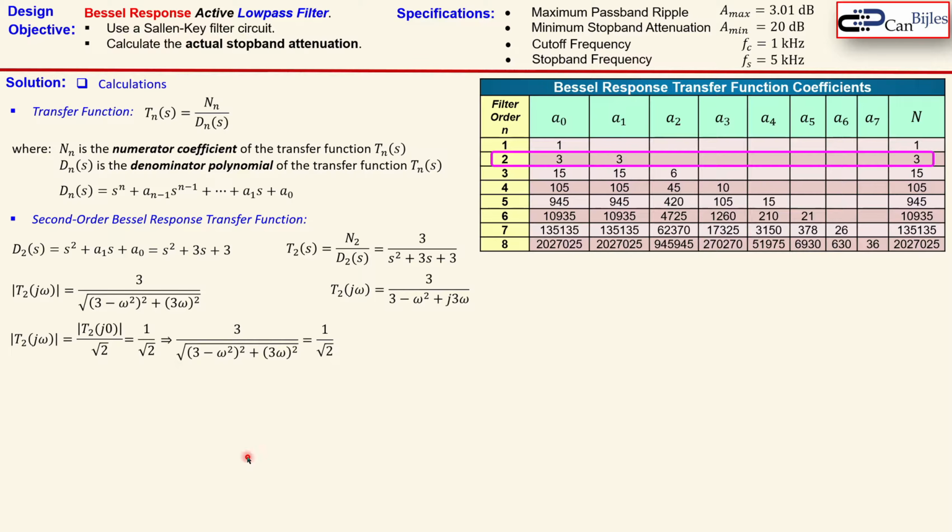If you now solve this using a solver, or you can do it by hand, that will give you an omega which is 1.36165 approximately. This is actually a bit different in a more exact way, but this is good enough, and that will now be defined as t sub n, and that is the time normalizing or normalization factor. This is an important parameter we need to use in order to continue with the calculation of the actual stop band attenuation.